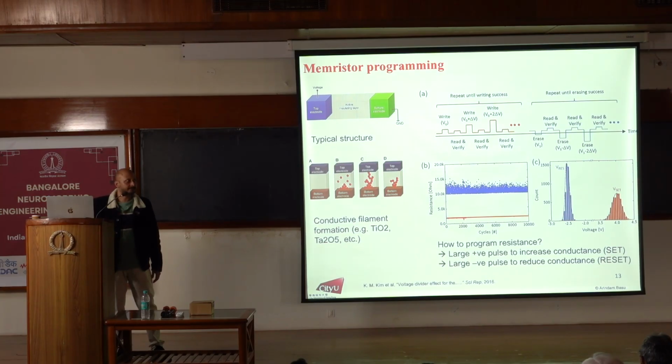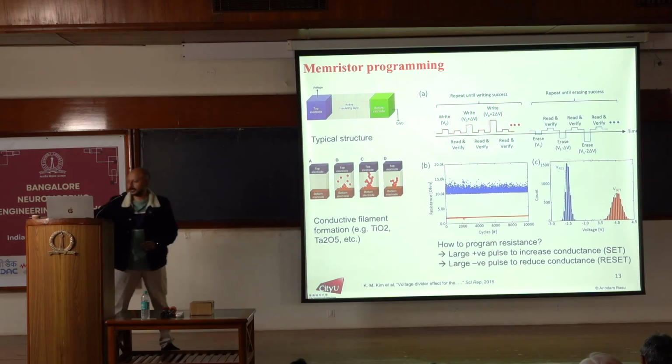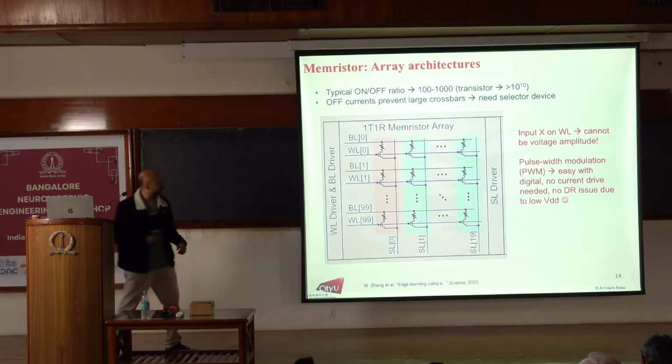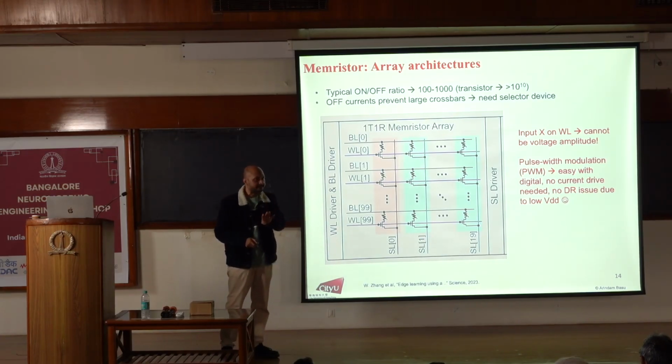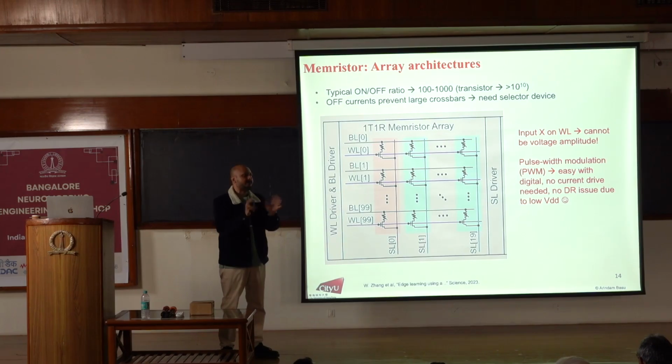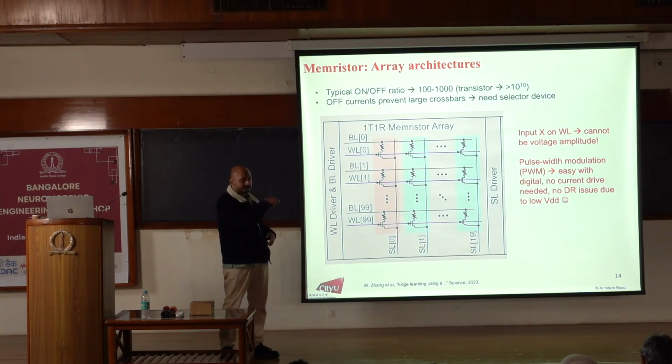Yeah, so for example, if you had a digital value at the outputs, what happens at the outputs here? Now you don't have a transimpedance amplifier. Instead, you have, let's say, a capacitor that's integrating the current that's coming in. So then you can see that the delta V on the capacitor will be proportional to how much charge goes in. And the charge that goes in will be proportional to I times delta T for each of these devices. And that delta T is your X.